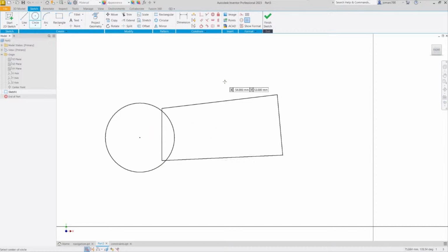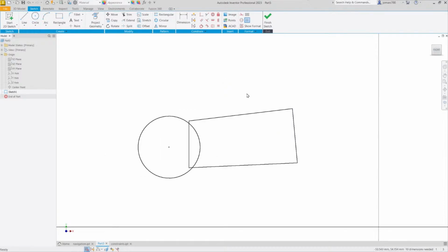Left click. Hit escape. Next, how about utilizing an arc? Heading up. Selecting 3-point arc, I'm going to left click at this corner, left click here, move to the right, and left click. Hitting escape. Let's create another circle, and this time using the keyboard shortcut, it's Control, Shift, and C. Creating a small circle here that will serve as holes, hitting escape.